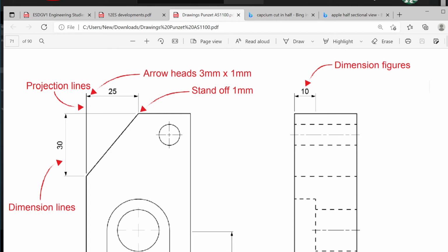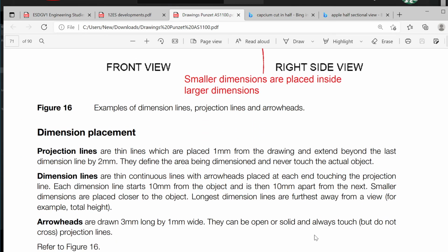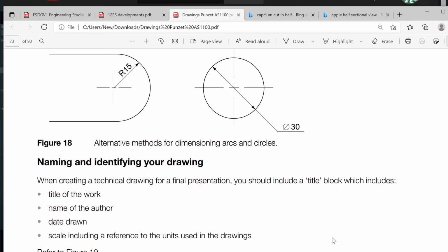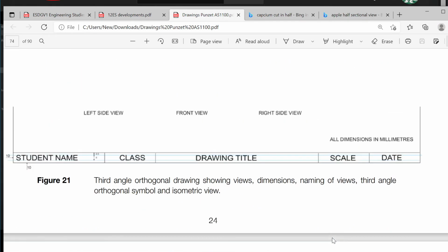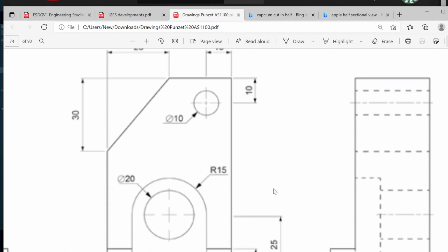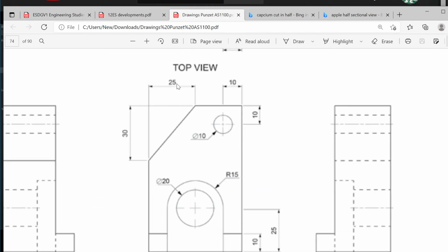I just want to say though, it's just so much easier to remember to the left, right? Like Beyonce, everything in your bag in the box to the left, everything that you own in the box to the left. That's how I think you should do it. Just showing here, to prove that, again, all the dimensions are above the line or to the left of the line. And they're always written as if they're on top of the line.